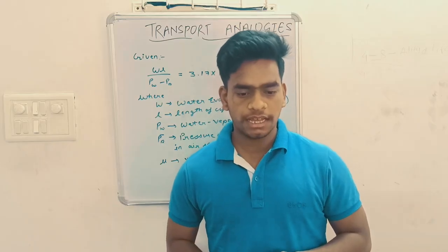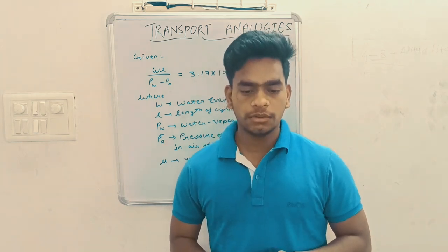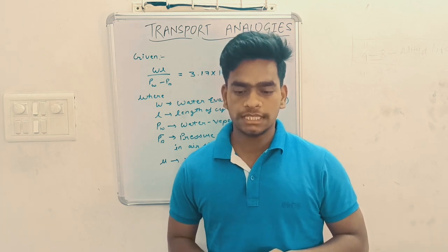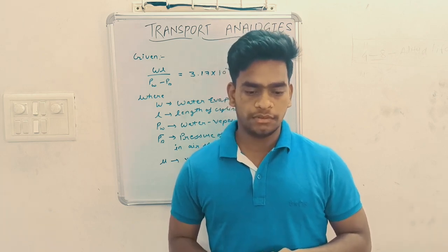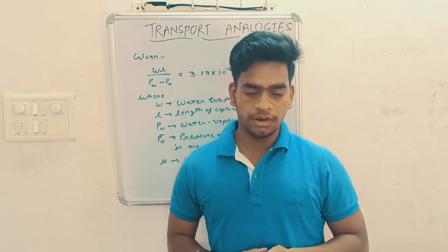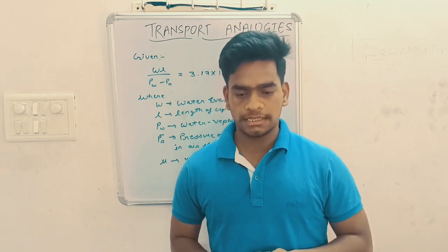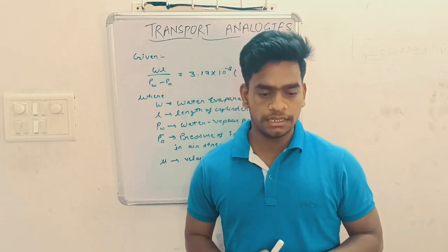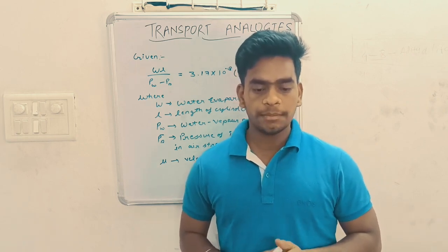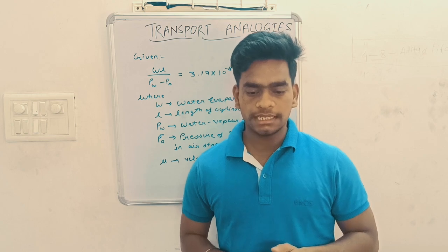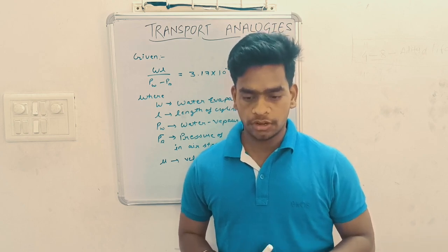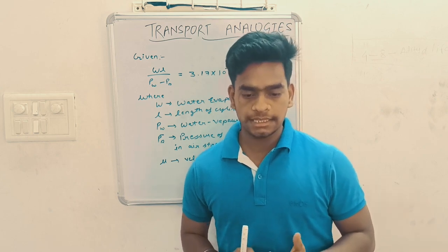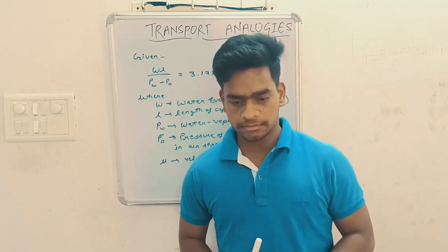In this question, we are asked to transform this equation into a dimensionless form, specifically involving the Reynolds number based on cylindrical length. The system involves air as the gas and water as the evaporating substance, and we are given the properties like density, viscosity, and diffusivity. So the goal here is to take the empirical equation and express it in terms of dimensionless groups such as Reynolds number, Schmidt number, or Sherwood number. This is a classical dimensionless analysis and correlation derivation task.